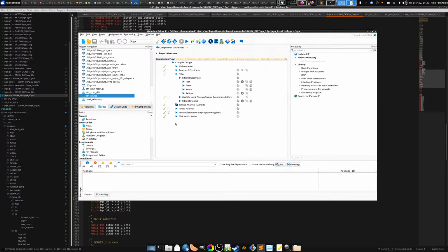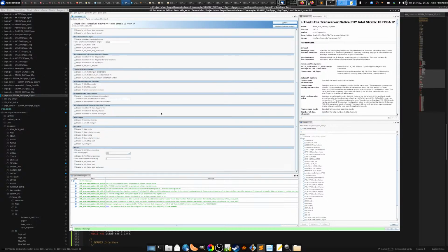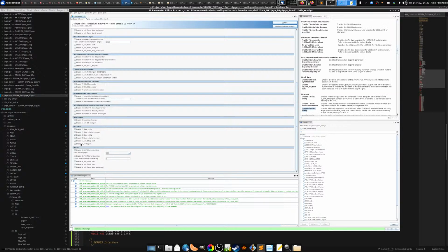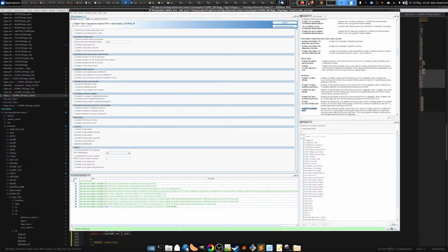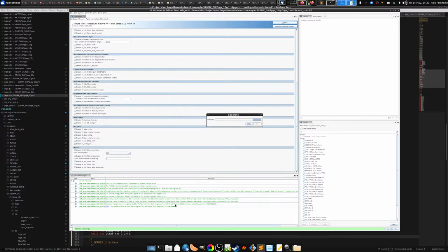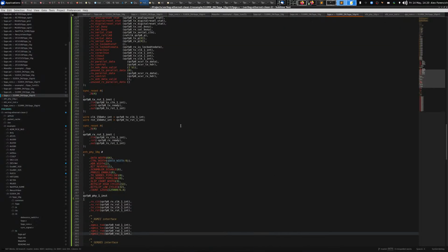I forgot to check a box again. Okay, fair enough. Let me go over to, I think this was under enhanced PCS. Yeah, okay. RX data bit slip and RX bit slip. There we go. All right. Okay. One more shot here. I think I have all the settings correct. Bit slip port is enabled, and that will regenerate. I'll have to add that in a second.